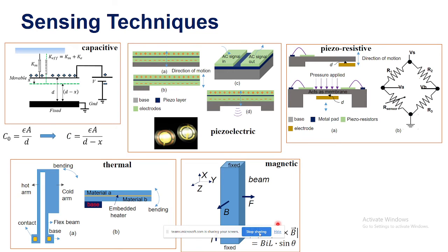Right, right. When I was explaining this part of the Wheatstone bridge, I briefly mentioned in one sentence that the advantage is that the reading will be insensitive to, let's say, temperature and pressure changes. In the bridge configuration, all the resistances experience the same changes in their values due to, let's say, temperature change. So there will be a combined effect on the output, the voltage difference will be zero, the net effect will be zero. But in the case of a simple potential divider, if the resistance changes due to temperature, the output varies with respect to temperature.